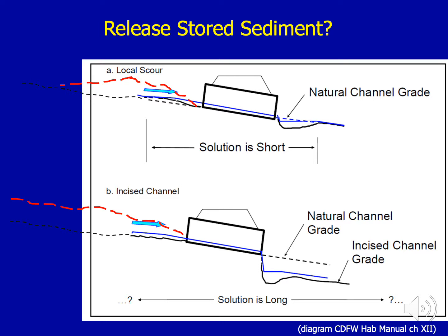So it often comes to the question of culverts generally, when many times they're undersized, they are sediment traps upstream. You get aggradation happening upstream in the process. So if you're replacing that culvert, opening it up, you are often having to address the question, do we release the sediment that's stored upstream in the culvert or not?